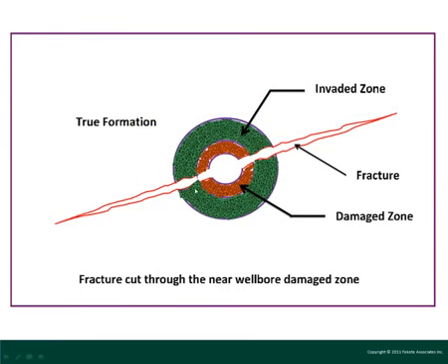Now, in reservoirs where conventional drawdown buildup tests require long-term shut-ins, such as in shales or tight gas, unconventional testing provides reliable estimates for key reservoir parameters from data normally used solely for fracture treatment design. Now, a mini-frac test is an injection fall-off diagnostic test performed without proppant before a main fracture stimulation treatment.